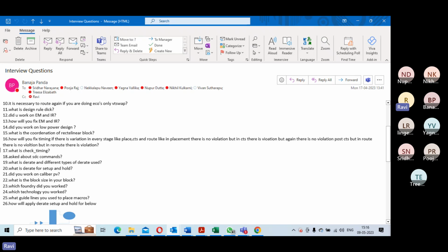Against those rules, the rule deck, you are checking whether your design has been implemented exactly as per the fabrication requirements. It could also be redundant vias requirements, min width, different rules, all that has to be taken care of, including double patterning, etc. So this needs to be done.